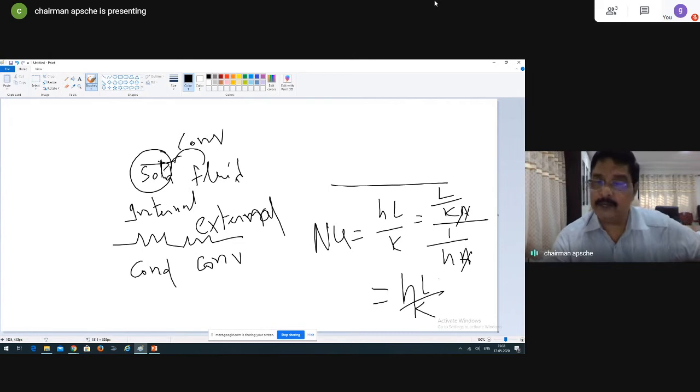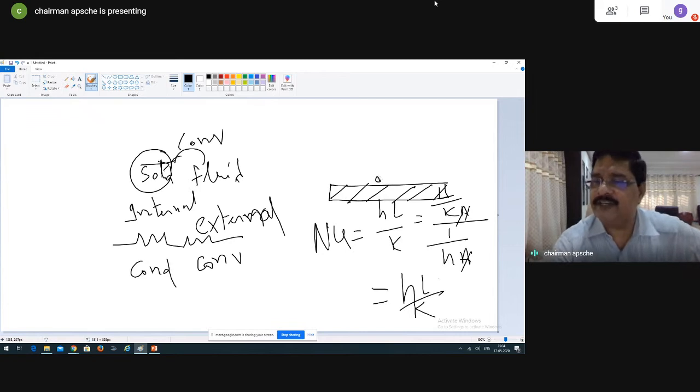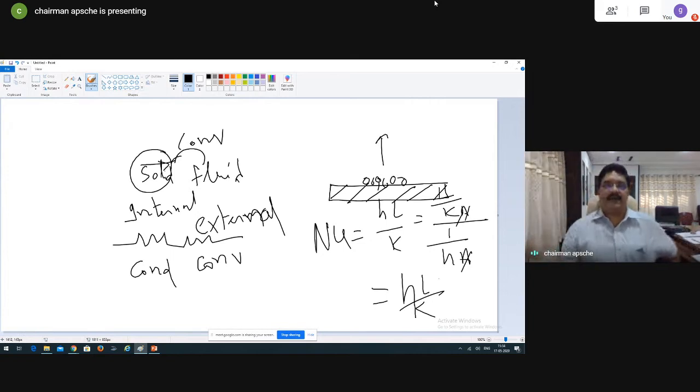Now, when I am talking about Nusselt's number, please remember, irrespective of whatever solid is used, don't worry whether the solid is copper or iron or brass or aluminum. Convection is a surface phenomenon. Please leave it to that discussion. When convection is happening, I said those no slip condition molecules initially participate in convection heat transfer. They take the heat. From there, it convects heat onto top.